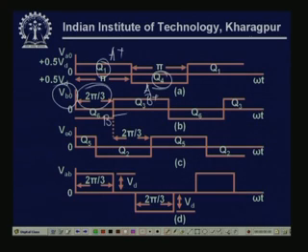Similarly, this is Vc0, which is C plus and C minus, and these are also switched. Then how will the line voltage look? The line voltage VAB, which is applied across the motor, is nothing but VA0 minus VB0. So now look at VA0 minus VB0. This is 0.5 Vd, and suppose we are switching between plus and minus, so minus 0.5 Vd.